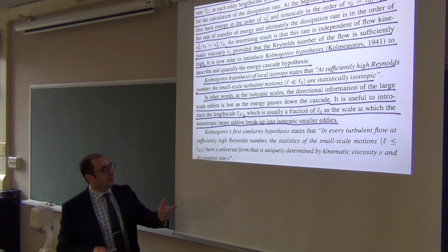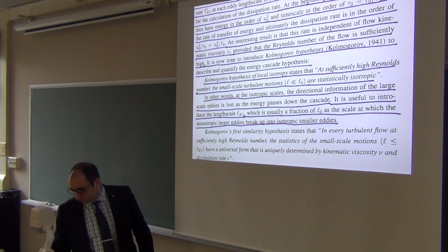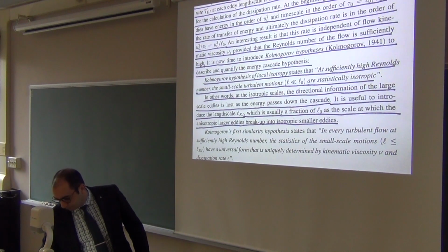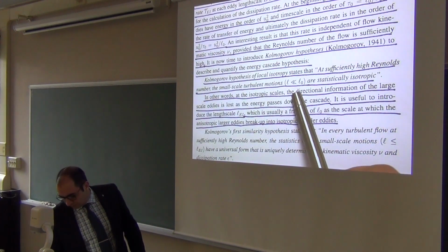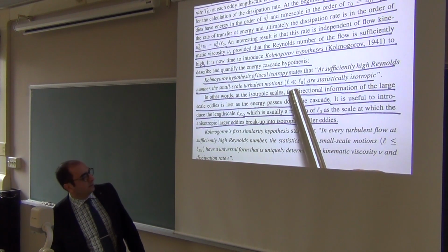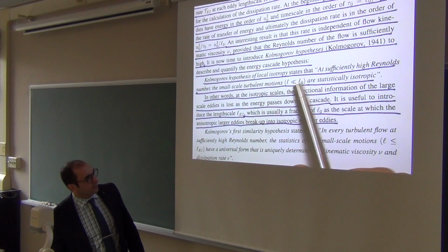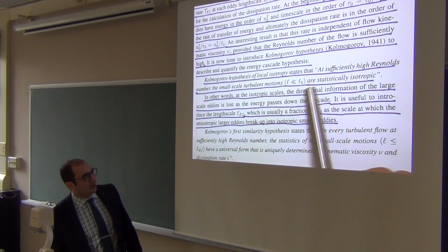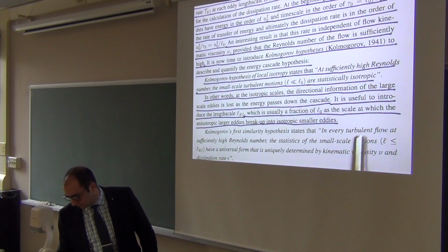If you change the reference frame, you're going to calculate different components of Reynolds stress, for example. But at smaller scales, if the fluctuations are smaller than the largest eddies, then at higher Reynolds number, the turbulence is statistically isotropic. If you rotate the coordinate system, you get the same components of the Reynolds stress.